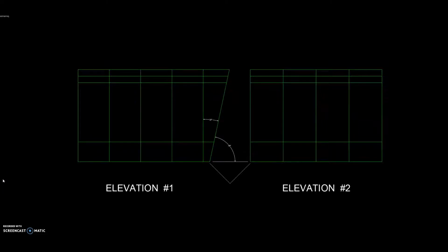This video is to show you how to find the miter angle and the tilt in a compound miter through projections using AutoCAD. For this demonstration, let's pick two planes, or more specifically, two elevations, that in plan view will be joining, creating a 90-degree outside corner.